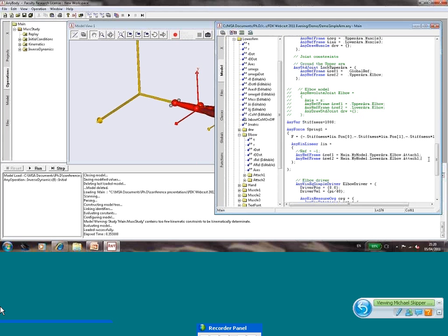The last little thing we will do, just to have it in the model view when we load it, is that we'll tell the system to actually draw it. And the way to do this is putting in what's called an AnyDrawLine. This one will draw a line between our two nodes. It needs two arguments. It needs to know the thickness, which I will just put in a value for, and then it needs a color, which you get by RGB, which is red, green, blue, and we will put 1, 0, 0, which will give a red line.